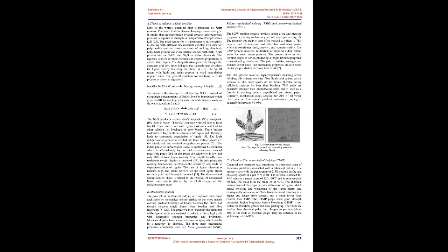Good paper can only be formed by pulp fibers which have collapsed lumen and low lignin content. V. Pulping process. In the pulping process, wood is converted to fibers (Fig. 6), i.e. wood or any other fibrous raw material is reduced to a fibrous mass by rupturing the bonds systematically within the wood structure. 21.